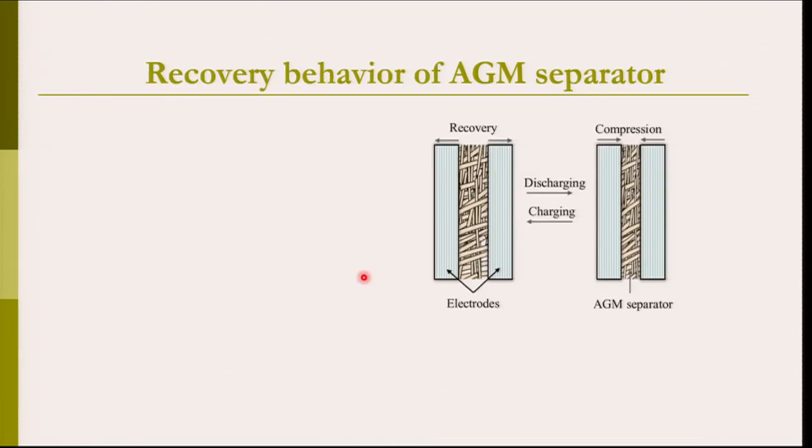So, now we can also make use of the meso domain for the recovery behavior. And how do we do that? So, during the recovery stage, the compression load is released gradually in succession by reduction in the magnitude of Cj, which is the average force applied to a defined fiber to fiber contact in the meso domain of volume dV. So, in such a case, the behavior of slipping contacts would differ from the compression state.